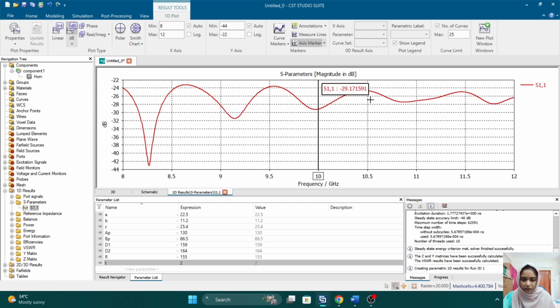So what does it mean? It is the return loss, the S11 with this value at 10 gigahertz, and the deepest loss of minus 42 dB near 8.3 gigahertz. We can see that if we change the marker to the minimum point, we can see that at 8.2 gigahertz we achieved minus 43.08. So that is ideal for an FMCW radar switch with a minimal amplitude ripple.